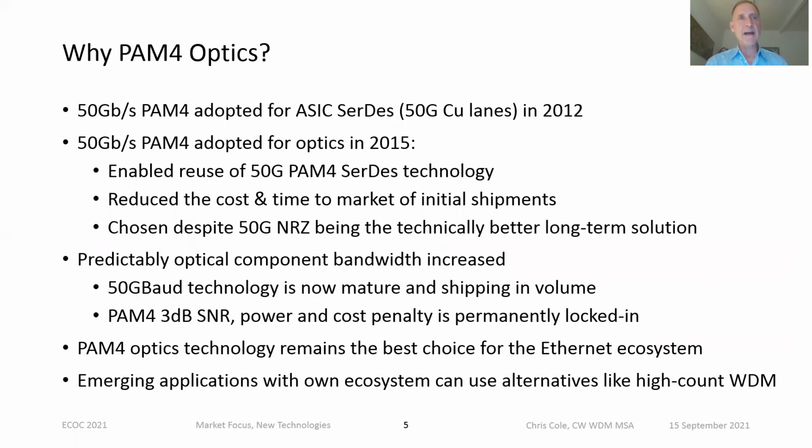So why PAM4 optics? Well, 50G PAM4 was adopted for ASIC SerDes, 50G copper lanes. This is between the ASIC and the module, as well as others in 2012. As we saw earlier, that's a sensible decision. That's what Shannon would suggest we do.